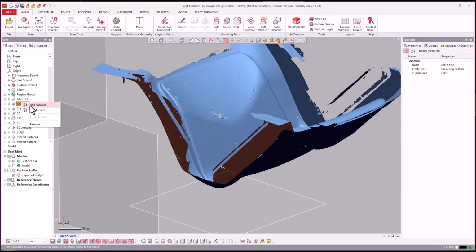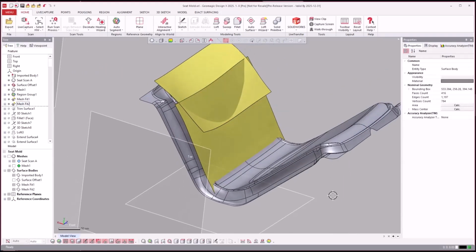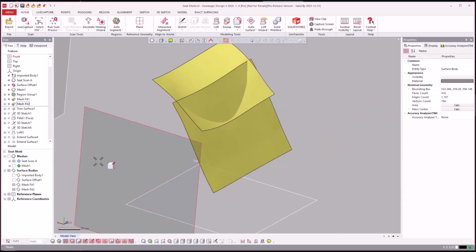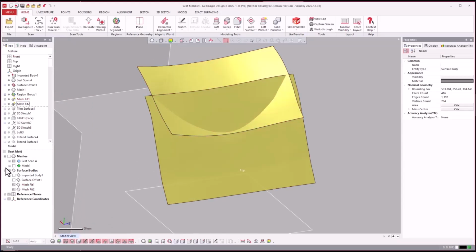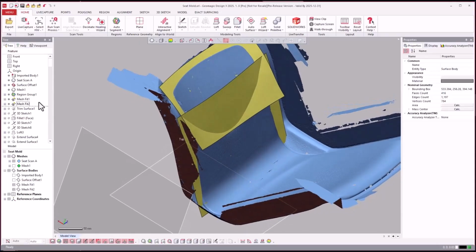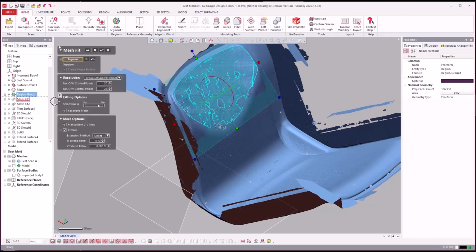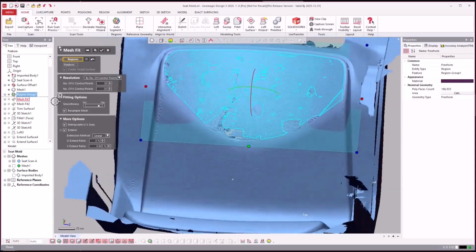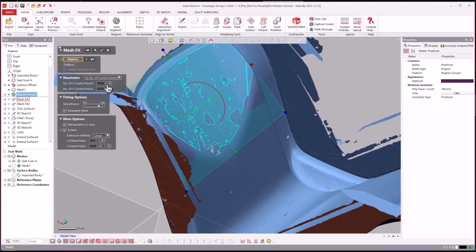First of all, we're going to do a couple mesh fits, and I'll just turn off the imported geometry. So you see that they did mesh fits on the scan data there. I'll just pop that on, and if I just double click that, you can even edit the mesh fit. I don't know if I've brought that up in our webinar before, that you can see the data that was used to extract that mesh fit, and you can even make updates and changes to it.